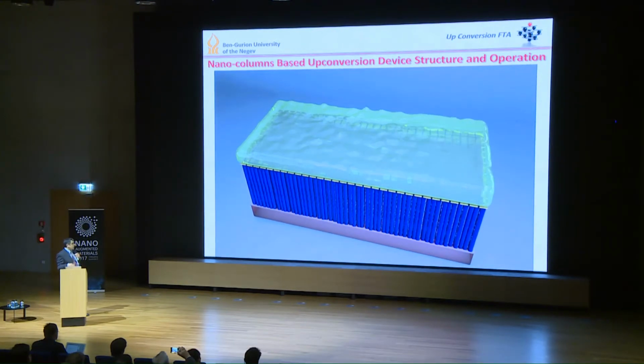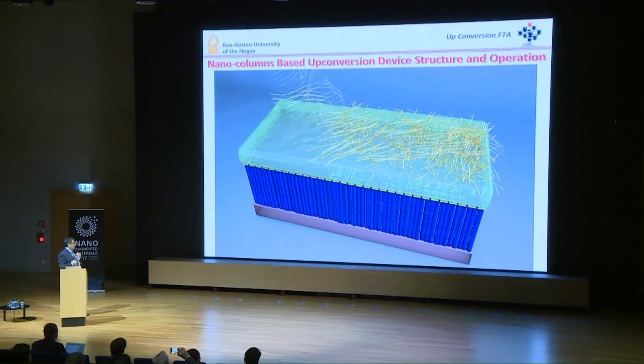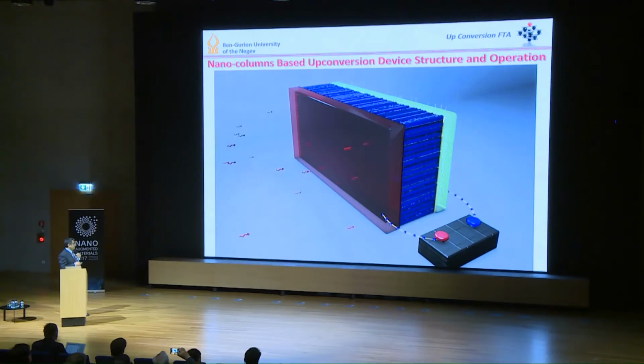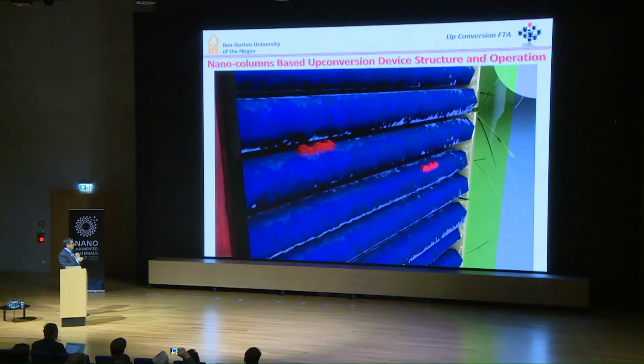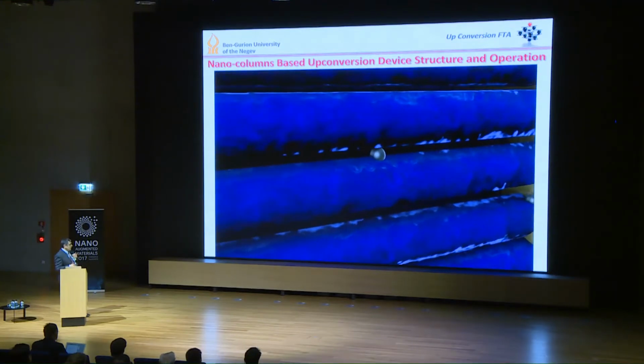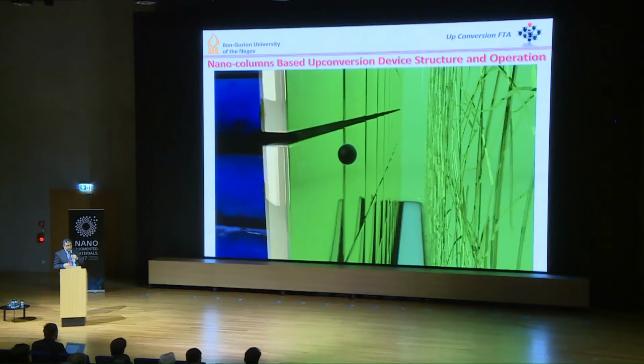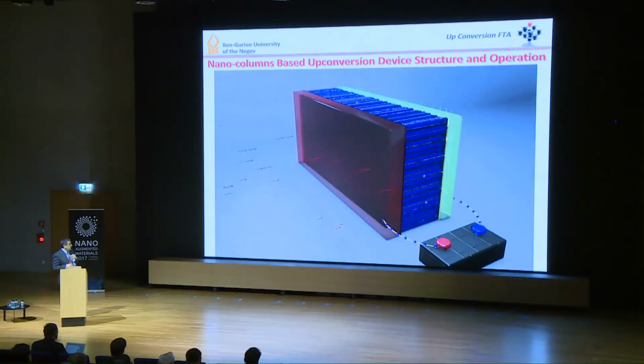And on top of the OLED, we can spray coat the carbon nanotube or nanowires or any transparent cathode that we already treated with a low work function, high lateral conductivity, and of course, high transparency. And then we have to apply the bias. We are applying the bias, and then we have infrared light coming from one side, and an infrared image is transmitted, and a visible image is transmitted from the other side. So this is the principle of the idea here.